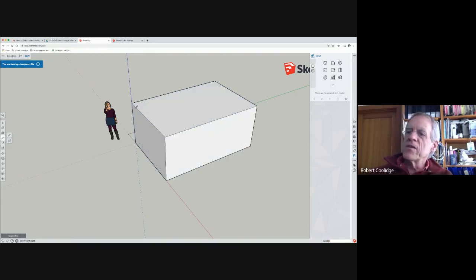Here's the fun you can do. You can draw on the surface like this. Now it's automatically cut. There's an intersection here, and it automatically cut. You can see that that's a surface and that's a surface, a separate entity. You hit the push-pull again, and you can make these shapes and push them about.